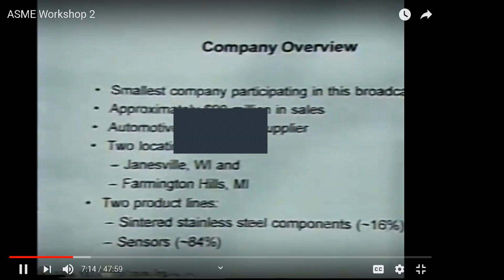Back in 1989, there were basically two types of pressure sensors being supplied to the automotive market in production. These were based on strain gauge technology and capacitive-based technology. Both of these are macro-based type sensors. That is, you can actually build these with your hands. You don't have to use photolithography to build these sensors. Both of these are still currently in use, although they are slowly being phased out in favor of some of the MEMS type sensors.